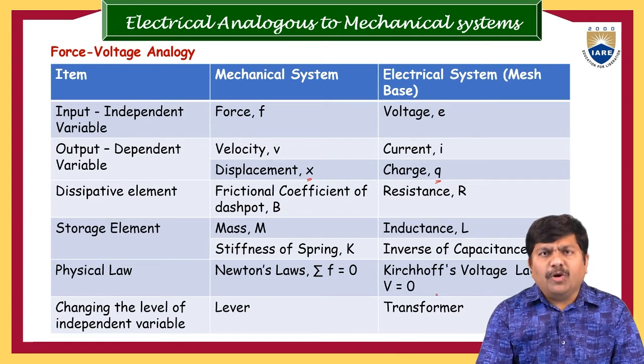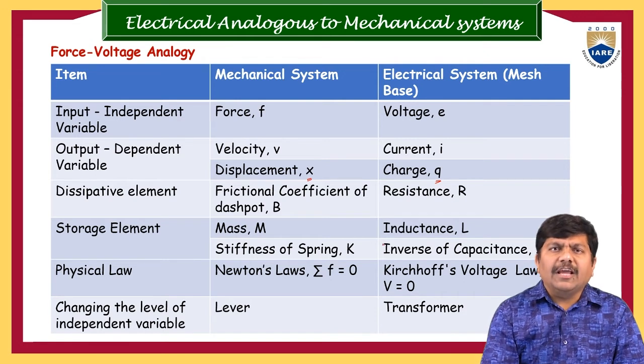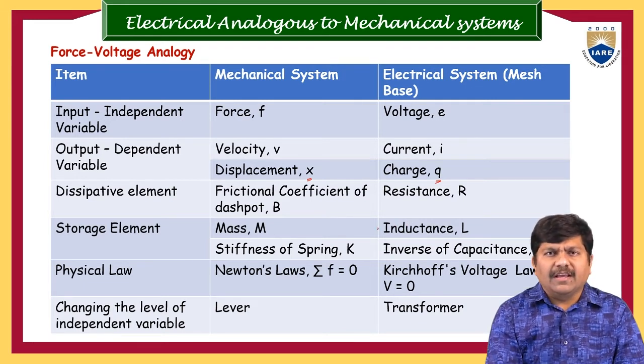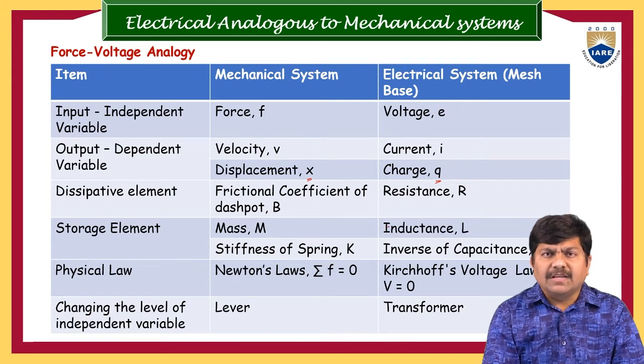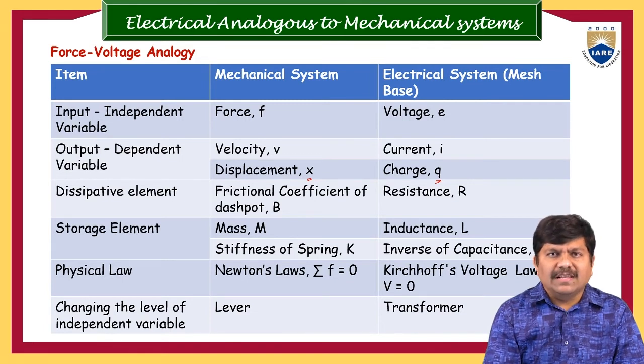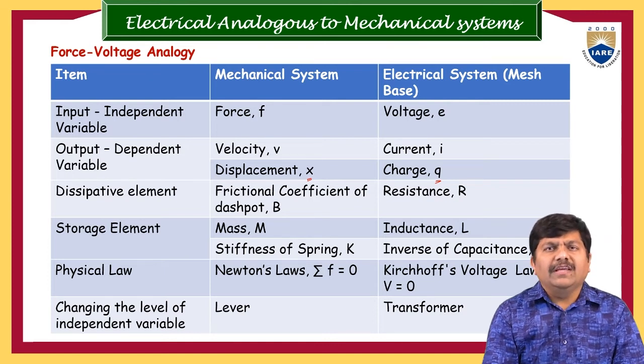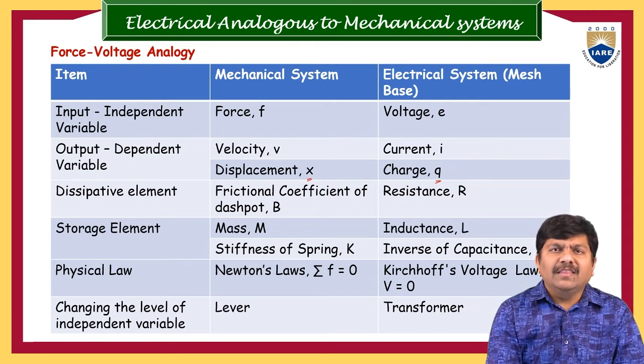Now, one more important point we can observe from this description: what technique have we used, mesh analysis or nodal analysis, to determine the electrical analogy of the mechanical system in this presentation? It is the mesh analysis we have used. So, in this force-voltage analogy, we can determine the electrical analogy of the mechanical system by using mesh analysis. Now, this also we achieved. One more important remarking point here: the number of mass units in the mechanical system is equal to the number of electrical loops.